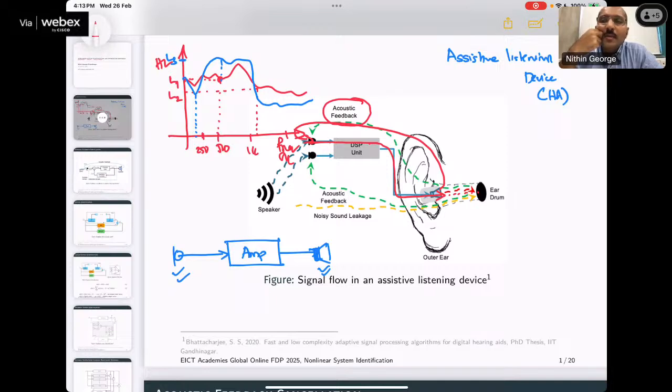So what they typically do is that they go and reduce the gain. They reduce the gain, that is one. Or you move away. So how it happens is, you are speaking on a mic and there is this loudspeaker somewhere over here, and you move the mic near the loudspeaker. So this feedback loop is created and the sound is getting amplified, and you are getting this beep type of sound, or the amplifier is getting saturated.